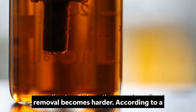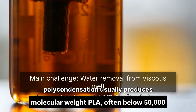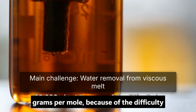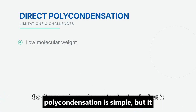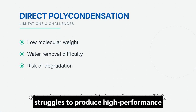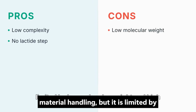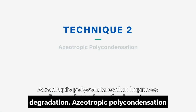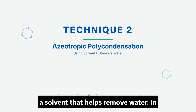According to a PLA synthesis review, direct polycondensation usually produces low molecular weight PLA, often below 50,000 grams per mole, because of the difficulty in removing byproduct water. So direct polycondensation is simple, but it struggles to produce high-performance PLA. Its advantages include low complexity and potentially lower raw material handling, but it is limited by low molecular weight and high risk of degradation.